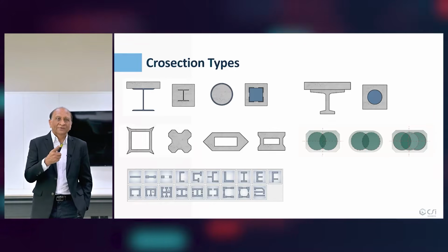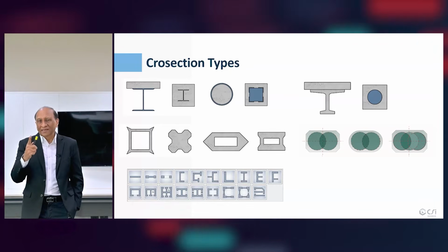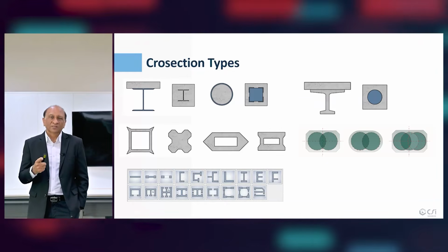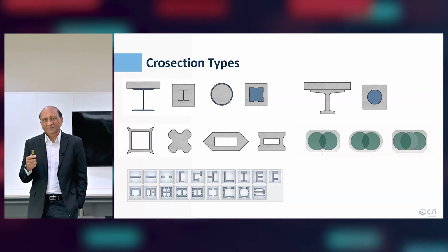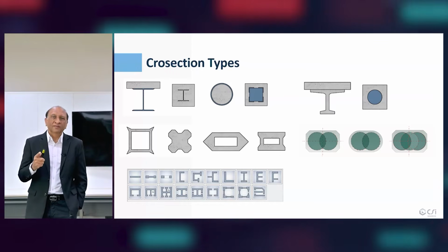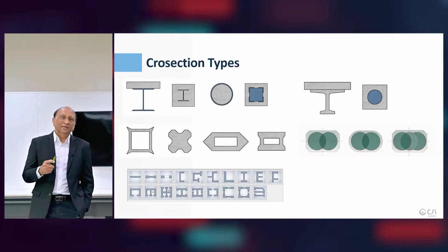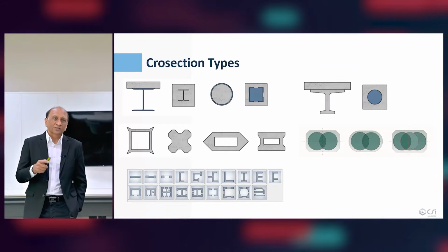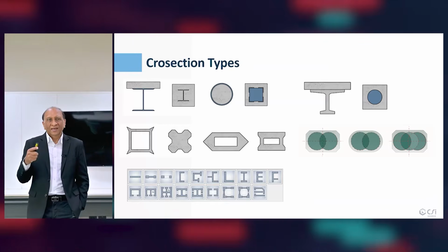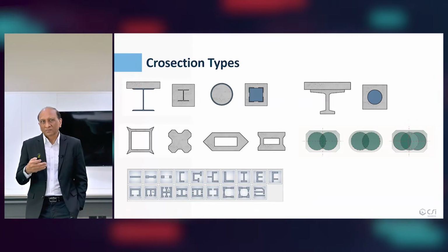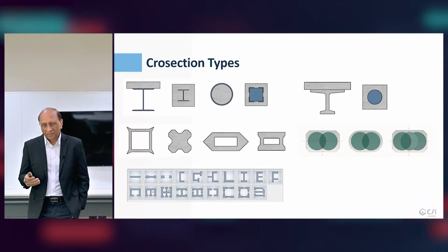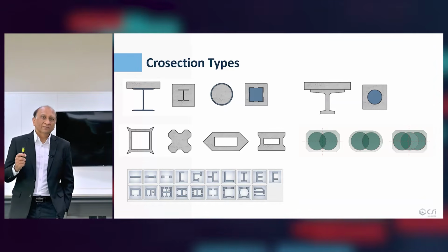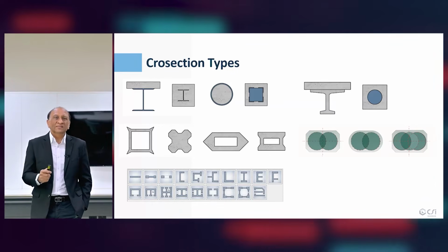If it's a bridge pier, it can be like that. Shear walls will be like that. And then even confined, the green ones that you see here, they are the confined columns coming from AASHTO and other Caltrans agencies, which use special types of reinforcement patterns to create their bridge piers. So we can see here there is a large variety of cross-sectional shapes, configurations, and materials that are used. So now the question is, can we develop a unified equation to compute the basic capacity?